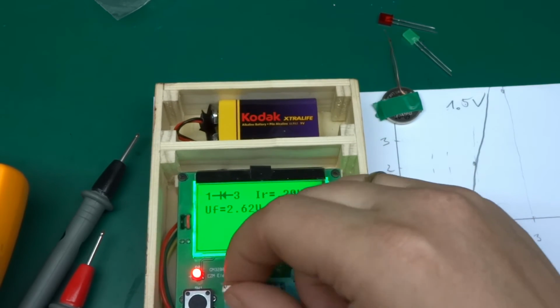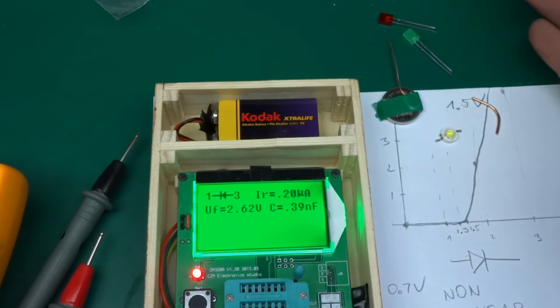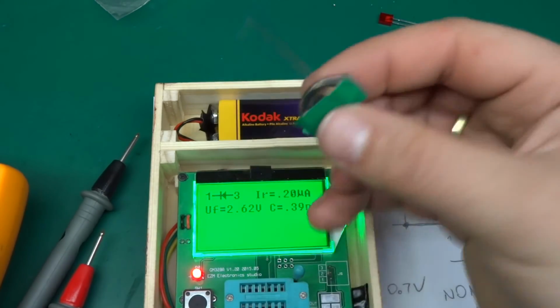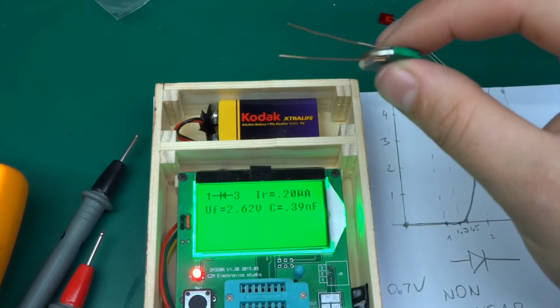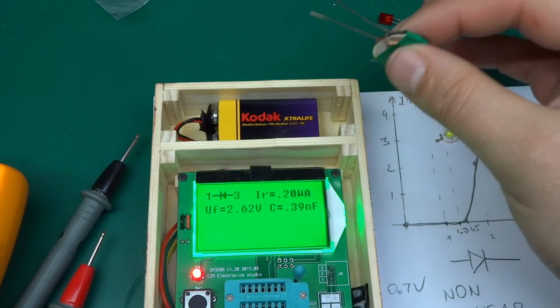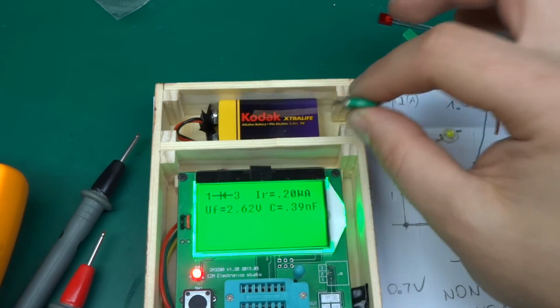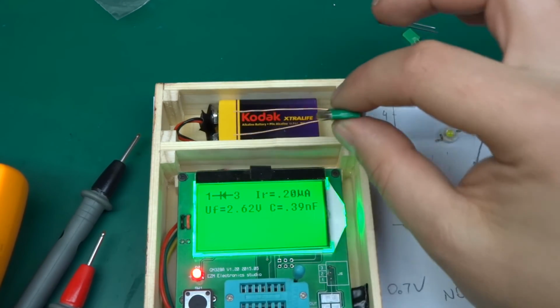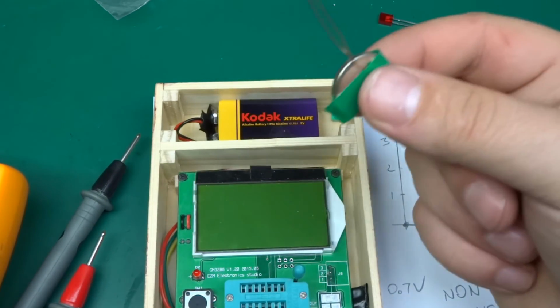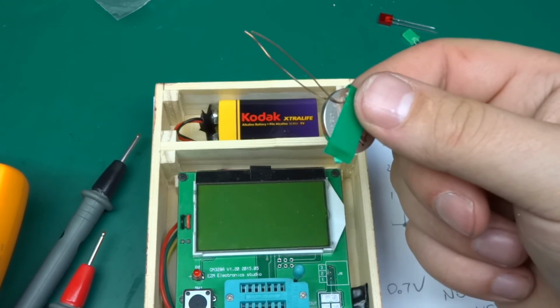And yeah, the LEDs are fine, they are working, and that's how you can measure them using just a simple button cell. So if you haven't got one, just put 2 AA batteries in series, that will do just fine. Just mind you, the AA battery has got quite a lot lower internal resistance, so with some small LEDs you can actually damage them by using 2 AAs.